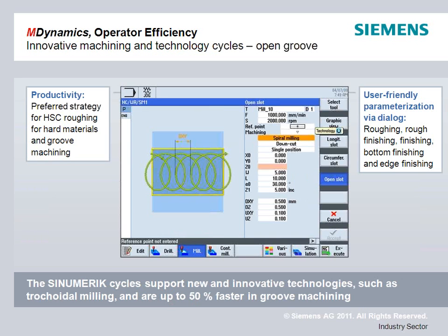One of the things that we've gotten from the cutting tool vendors is a cycle called trochoidal milling. You may be familiar with this because what it does is it effectively does an offset circular path through a part that is quite optimal for the chip load, helping you remove material faster and maintaining longer tool life. This can be entered right at the machine by your operator. So even if he's doing something simple, like we need this fixture made up for such and such, we need a piece of mounting made for such and such, and he just needs to clear out a lot of material quickly. Instead of having him say, yeah, I can program this on the machine, but it's going to be with a really inefficient path, we have functions like these trochoidal cycles built in so that you can do this in a very efficient manner.